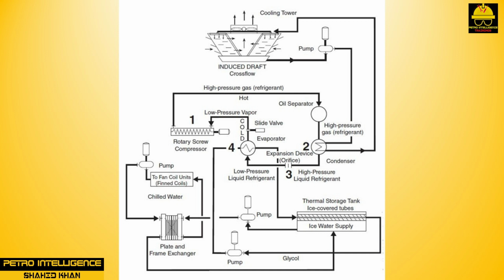At this point, we have a supply of liquid at elevated pressure and at about room temperature. To make it boil, all we have to do is release the pressure under which it is stored since room temperature is far above its atmospheric boiling point. One factor to keep in mind is that everything has heat content, unless it is at absolute zero, or -273.1 degrees Celsius, which is -460 degrees Fahrenheit. Air in a room has plenty of heat, that is why we can cool it with our air conditioners.